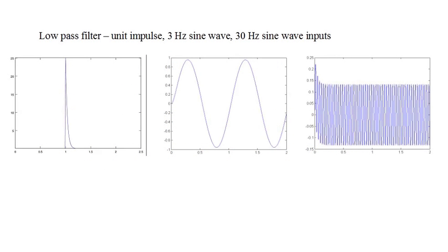Letting the computer do the rest of the calculations, we get the graph on the left. The other two graphs show the filter response for a sine wave at 3 Hz and a sine wave at 30 Hz. If you note the vertical scales on the graphs, you'll see that the amplitude of the 3 Hz wave is nearly full amplitude at 1 volt, while the amplitude of the 30 Hz wave is attenuated to 0.15. So the circuit is performing as a low-pass filter as advertised.